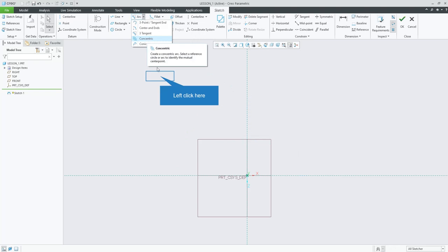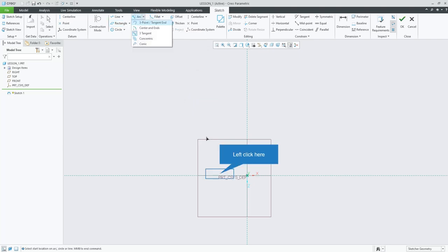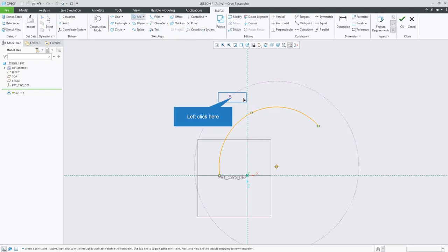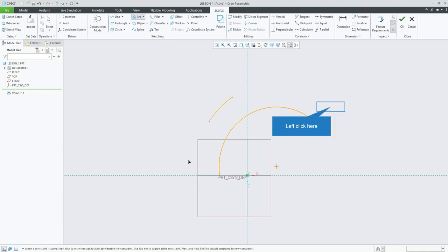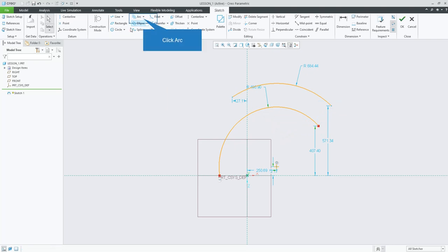And then the fourth type of arc is, again, concentric. So we're again clicking on the arc that we already have, letting our mouse go outward, clicking again to create the arc, and then it becomes like a center and ends arc, where you have the flexibility to put where the endpoints will be. Again, center mouse to get out of it.